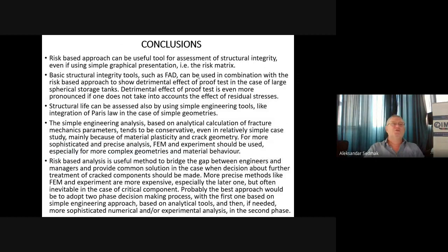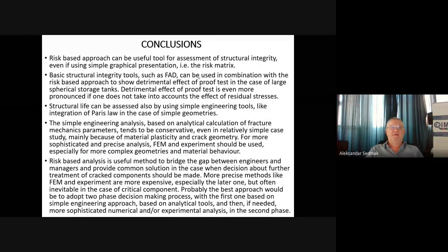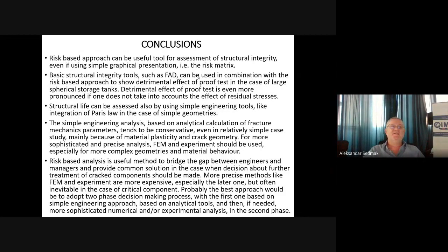So, in conclusions, I think I persuaded you that risk-based approach can be very useful tool for assessment of structural integrity, that failure assessment diagrams can be used in static cases, and that we should forget about proof testing for the critical pressure vessels.